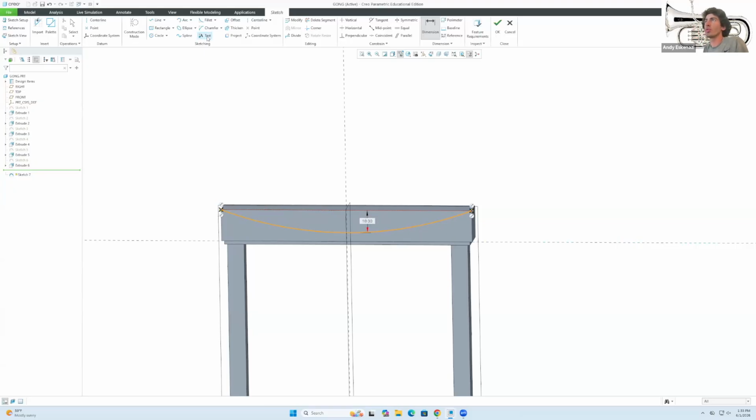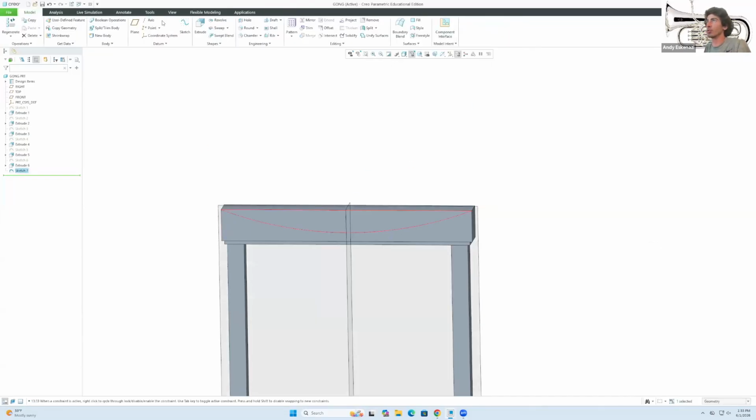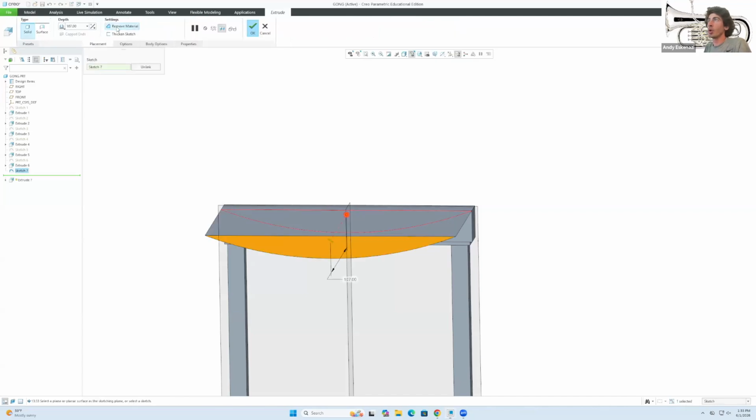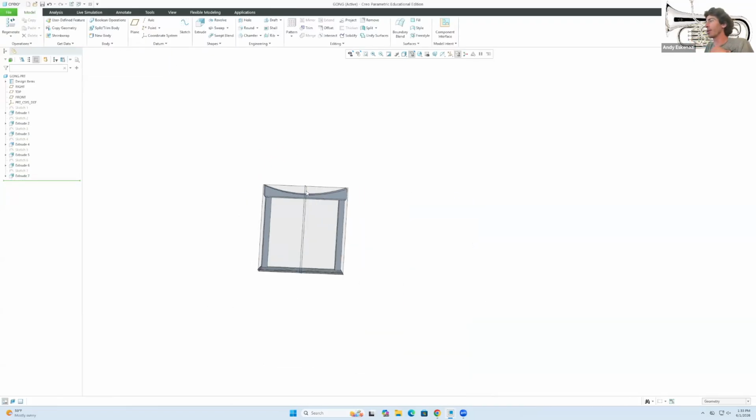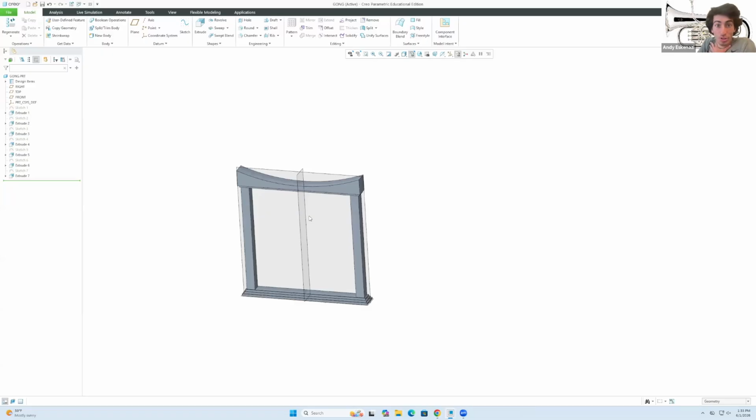Great. So what do we do? Actually, I do need another full line. That way that's gonna be shaded, because I go to here to okay, extrude, remove material, change the direction, do, I don't know, through all as an example, say okay. And now we got that part. Now, before we design the gong, let's add a couple of details here.